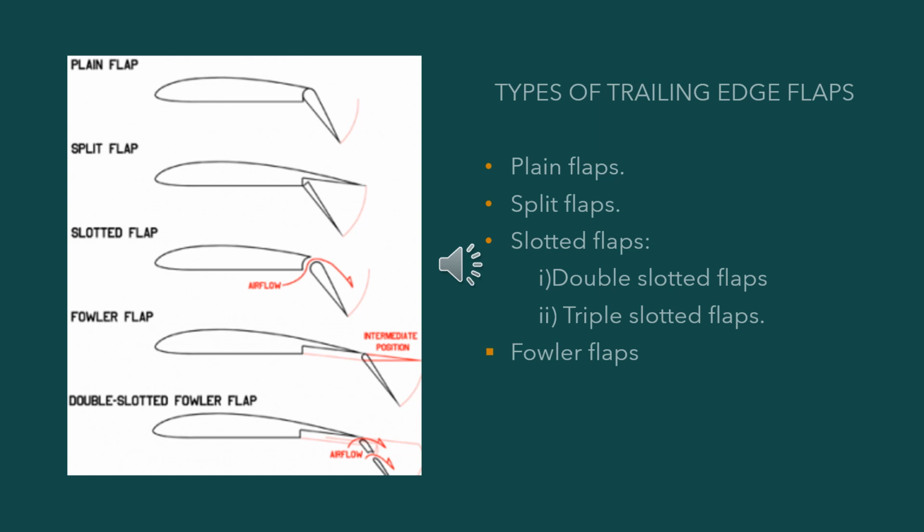In the first stage of Fowler flap extension, there is a large increase in lift but little increase in drag, making the setting ideal for takeoff in a large jet. As they continue to extend, the flaps move downward more and more, creating a little more lift but a lot more drag.